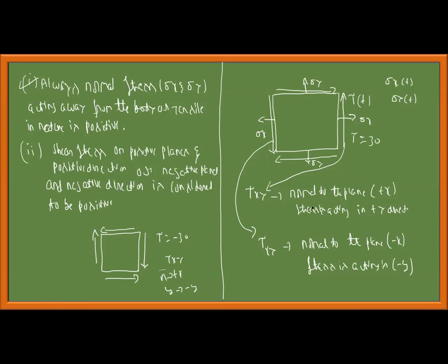You can say that if the signs of normal and direction are both positive or both negative, the stress is positive. If one is positive and the other negative, then the stress condition is negative. Okay, this you should know. The thumb rule is, if the stress is pointing upwards on the right hand face, not on the left hand face, it is positive.